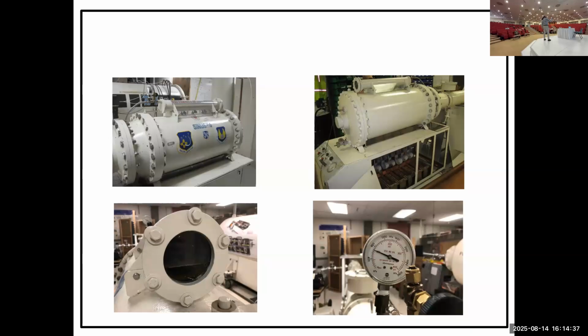So we reduced the transformer oil from here to a level where we could open the spark gap. Once we cleaned it and put it back together, we needed to add more oil to the tank. There is no way to add more oil if you have only one inlet. Any idea how to do that? How to add more oil to a tank? Pressurized. Yeah, with negative pressure, right?